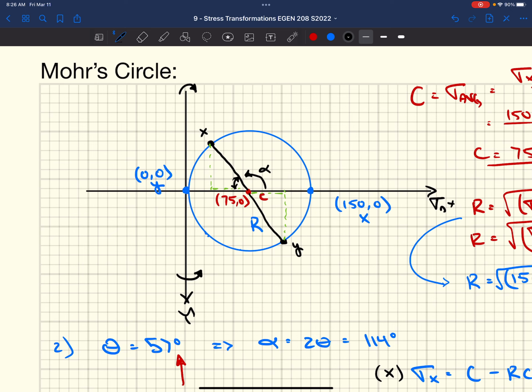To find the radius, do you need to do that equation, or can you just look at it? You could totally look at it. But it's not always as simple as the 2 points that you establish being along this x-axis. We're going to do another example where you start with a known stress state that has shear stresses in it, so now you're up here and down here with your initial points. And when you're up here and down here, it's just nicer to do it. But you can totally look at it, since it's essentially just finding the hypotenuse of a triangle, right?